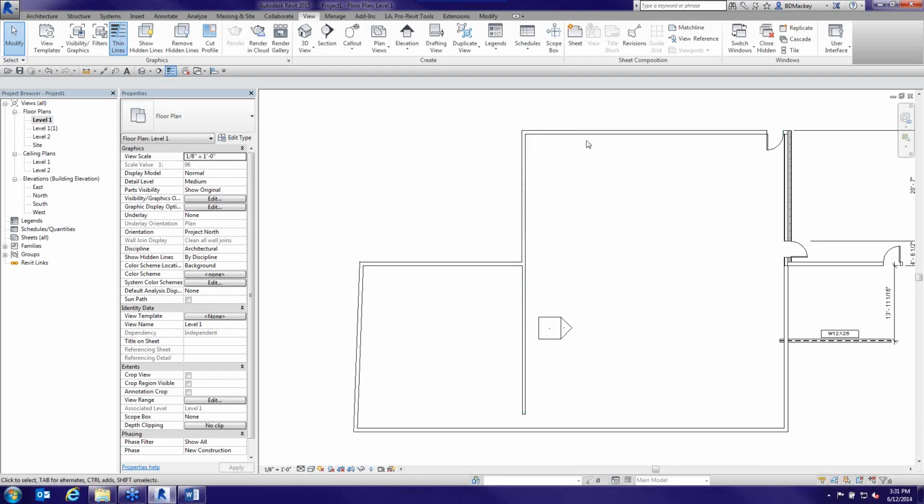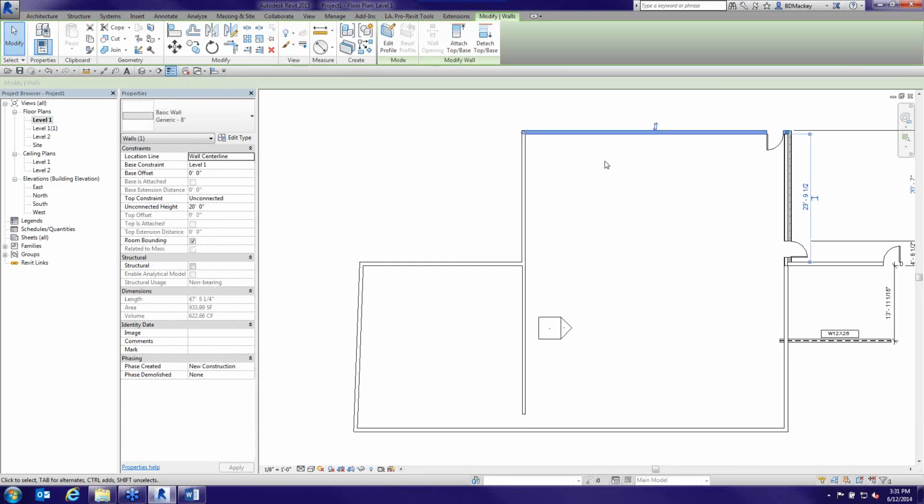Now, here's a tip that most MEP guys know, because this is an MEP feature. If I select one object and then come over here and tab, notice how it now grabs the chain of objects in between. Okay, this is huge. MEP, if you guys don't know about this, if you're trying to show what lights are going to have a switch, and you don't want all of the lights in the system, but only some of the lights to be switched, I want these lights on this switch and these lights on this switch, selecting one light, going over to the other light and hitting tab, it'll track the wires through and decide which ones need to be on that switch. So this is a big tip for MEP.